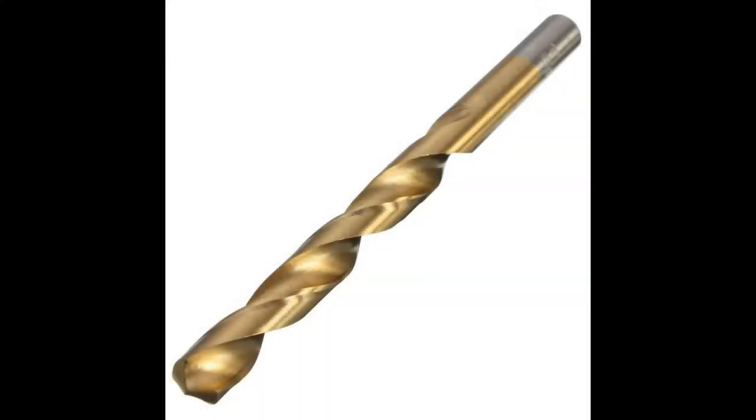So this image shows a standard drill bit. Now, drill bit technology has changed a lot over the years, and there's a lot of high performance drills, varying helix, which is the spiral you see there, and different tip geometry. A standard jobber length drill, which is your standard drill you'd buy at the hardware store, has a 118 degree included angle tip, and that's what we're using for this course. But a lot of the newer technologies have different angle tips, so you really have to look at the specifications for the tooling when you're going to purchase it.